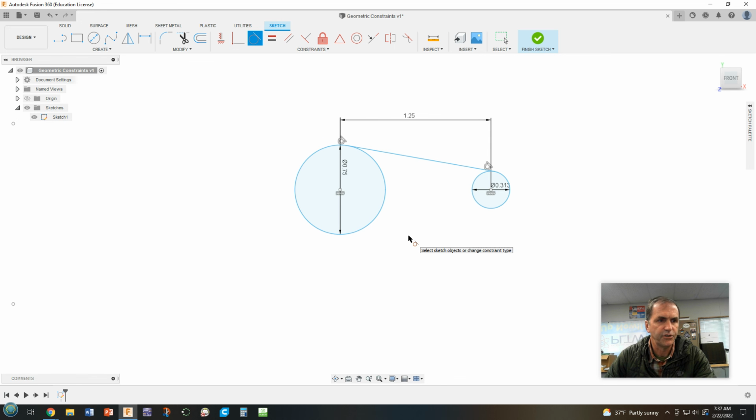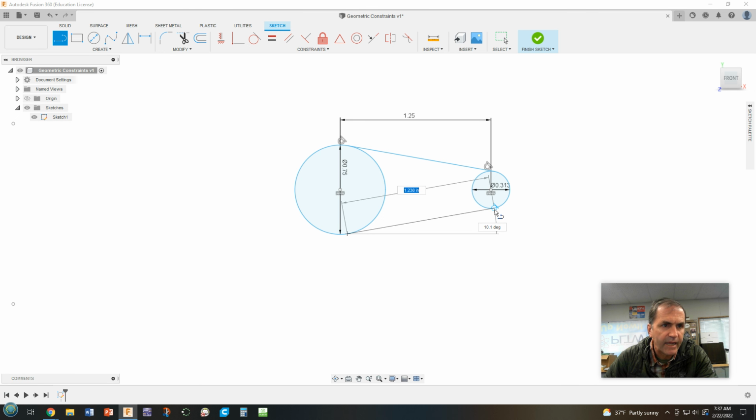Those tangent lines show up. Now we could also have made a line where we automatically, that little X means we're making that coincident. Now if you hover over enough, notice that that little tangent shows up, which means I am making that line tangent there. Okay, but I didn't make it tangent over here. So we've got to pay attention to that stuff. Make sure all those constraints are showing up.